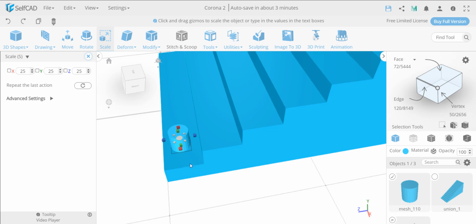So I'll need this to be going in a minimum of 5. So if this size is 25, I'll get it in 5, so it will be kind of the Y direction. Now it's flushed, you see, because I snapped it to it. So this is flushed, this is not good. So I need to put it in 5, but as I said before, if I'm going to scale it symmetrically, I'll need to reposition it. So it wouldn't be a good idea to position it first, I first need to scale it.